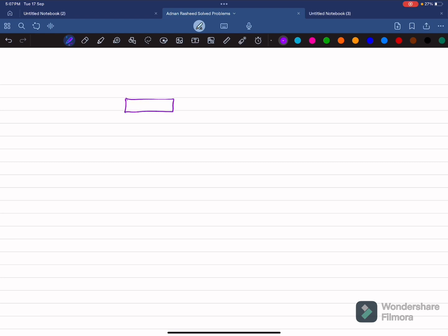So this is the beam. This is your point D where you have 3w naught into a, and there is a distributed load acting on it which is equal to w naught. This length is a. Clear? So when you cut it, you will have a shear force V. This is point E, so it will be VE, and you will have a moment ME.